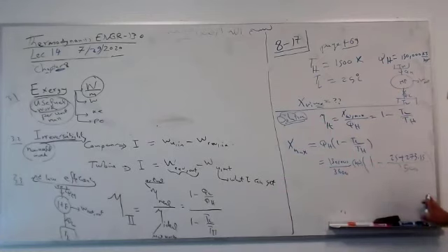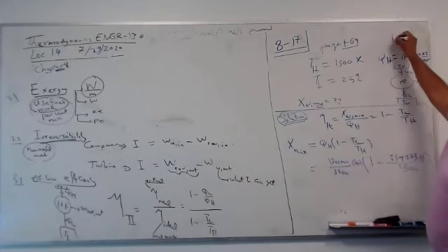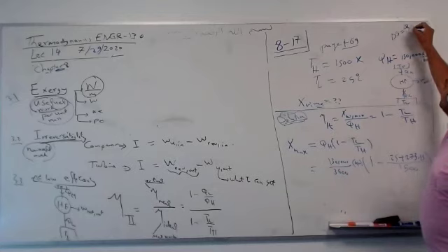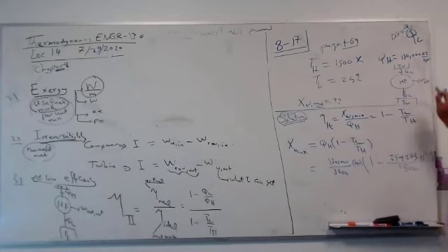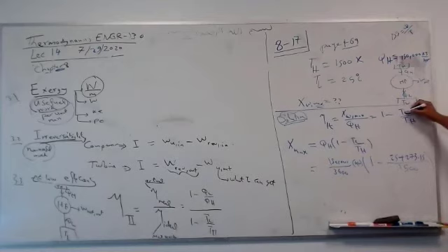This is Kelvin. This is good. But remember, if it's not Kelvin, you need to convert to Kelvin, especially when it's a ratio or multiplication, like delta S. Delta S is Q over T. I don't know why people love to substitute here by Celsius. This is wrong. Always Kelvin. Always substitute with absolute temperature Kelvin in T low over T high.